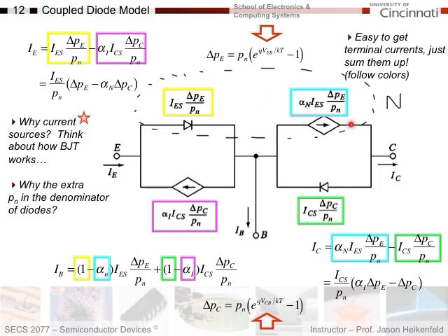Well, the equation should make sense. First, just look at the equation. The equation is basically what current is emitted. These terms are the same. So what current gets into the base and is emitted, times current transfer ratio, because current transfer ratio tells us how much emitter current makes it across the base to become collector current. So this equation should make complete sense.